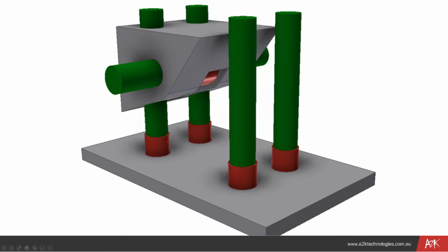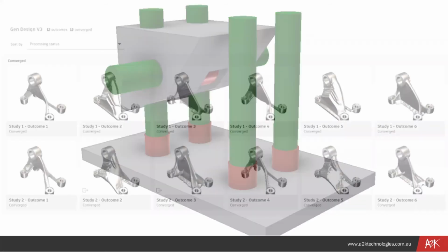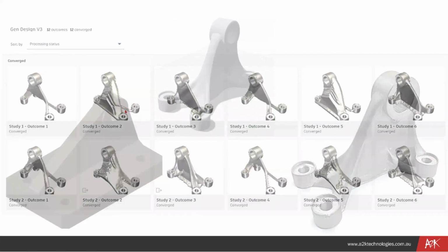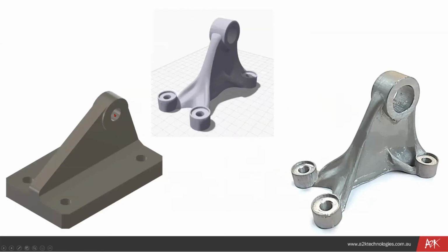We tell Fusion where the stress or the load for that particular part is. So again, on the particular clevis, obviously you would have a pin through this hole here that maybe takes 100 Newton meters or whatever it might be, as far as load is concerned. Now, what we do is we tell the system then that we're happy to preserve some of those areas, but basically what happens in between there is a bit irrelevant.